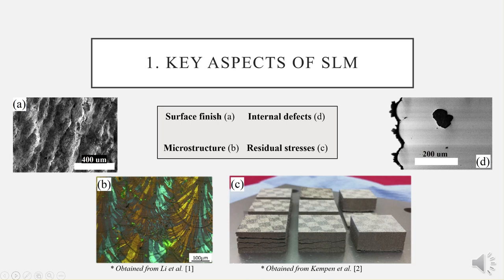When compared with conventional manufacturing processes, such as forging or casting, additive manufactured parts exhibit four main differences that drastically change their mechanical behavior. First, it is well known that selective laser melting imposes a very bad surface finish in the fabricated parts, as can be seen in Figure A. This terrible surface finish can, for example, enhance surface crack initiation, acting like stress concentration points.